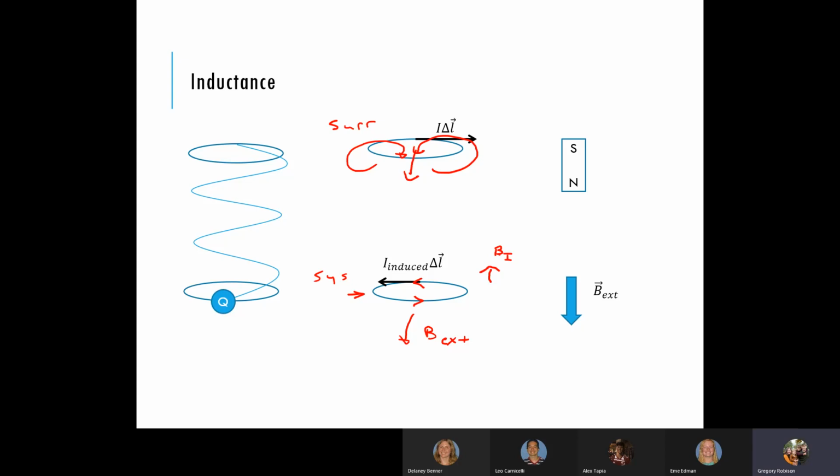And you have basically the basics of how a solenoid works then, how an inductor works. Okay. So you can think of every inductor as working off of the same principle. The magnetic field generated by one part of the inductor causes a different part of the inductor to try to oppose that change. And so for a brief instant, current won't flow through that inductor, just for a very brief instant.